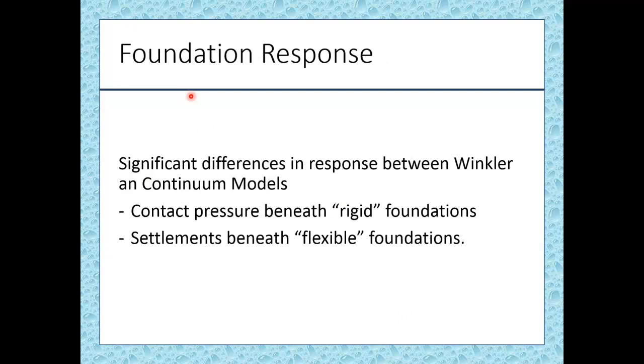Let's understand the foundation response. We need to understand that there is a significant difference in the responses between the Winkler spring used by the structural engineers and the continuum model used by the geotechnical engineers. This difference can be explained in more detail by using two examples. These are actually extreme examples: one is a rigid foundation, and the other is the settlement beneath flexible foundations. So we shall see the contact pressures and settlements between these two extreme situations. In further slides, let's go ahead.